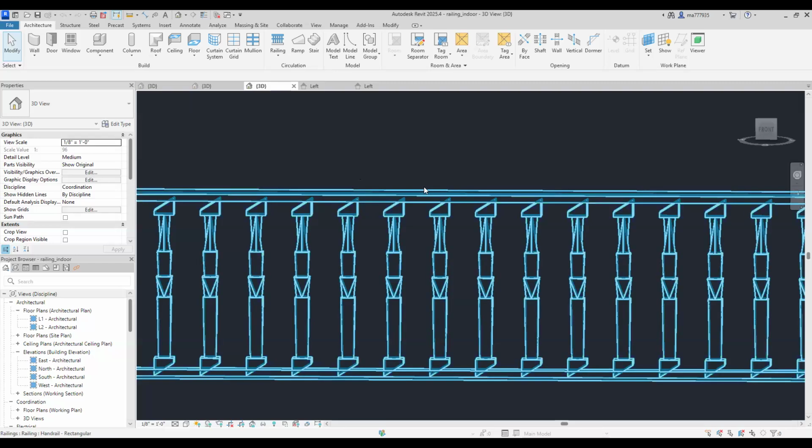I will tell you what I would do as a designer, especially at this stage of the project. I would give up on the angle and just let it bleed into the tread. So I would figure out the height difference thing, figure out why the height is changing from stair tread to landing, and not worry about the angle. That's just what I would do. No worries, and just let the bleed happen.